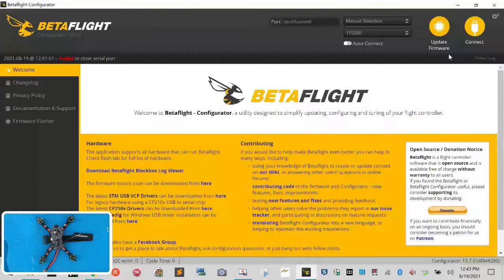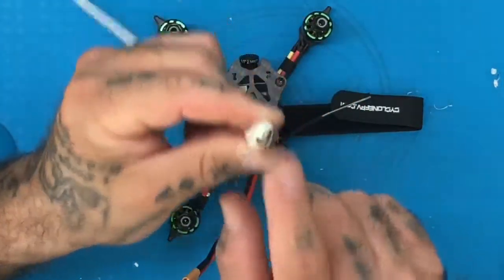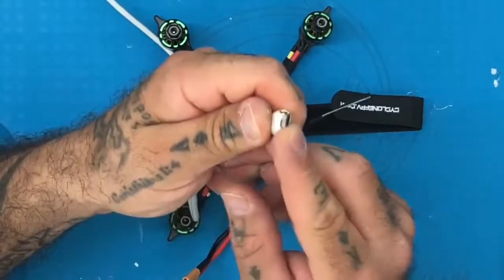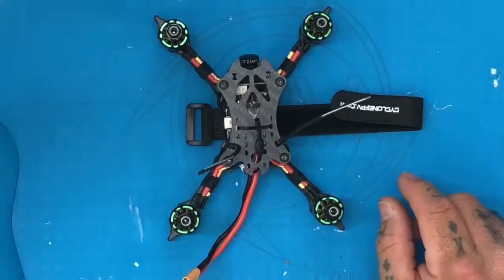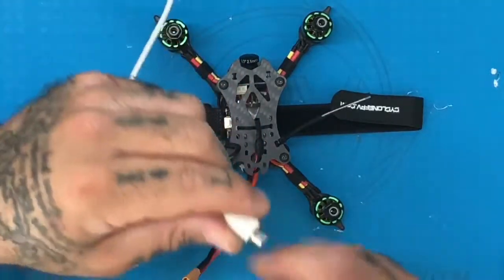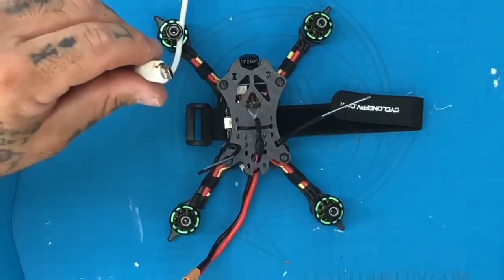The other thing you're going to need is, and I'll change the screens here, make sure that you have a USB data cable, micro USB data cable, not a charging cable. You have to have a data cable or else you will not be able to use this next section and program your drone. So any kind of Android device or anything that usually can plug into the computer or do updates on a phone or anything, usually will have a data cable. Make sure it's a data cable, okay? So let's go ahead and get back now.